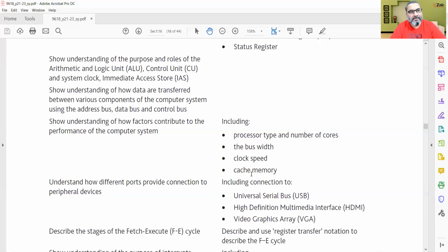You see, basically what happens, there is a problem in von Neumann architecture, and that problem is the delivery of the data and instruction from the RAM to the microprocessor. Think of it this way. Let's say there are 100 nanoseconds for one instruction. Basically what happens is that the travel of the instruction from the RAM to the processor takes 99 nanoseconds. Nano is one billionth of a second.